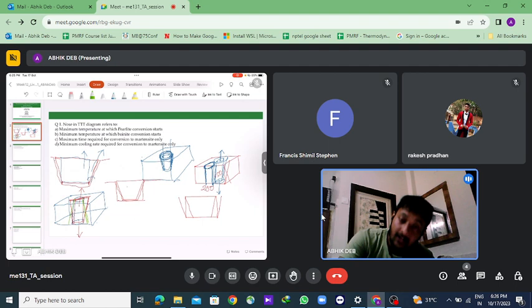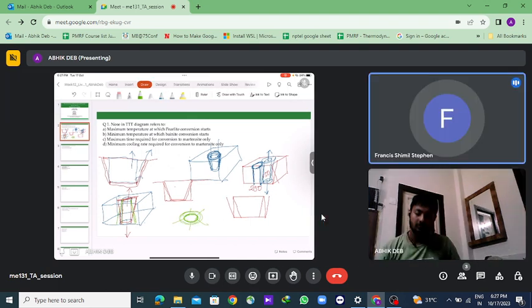Okay, so when we are giving that allowance, how will we be giving it? I mean, the taper allowance will be given last. In your previous lecture, an order was given, isn't it? The taper and shrinkage allowance were given at the same time. In which order will we be giving this taper and shrinkage?